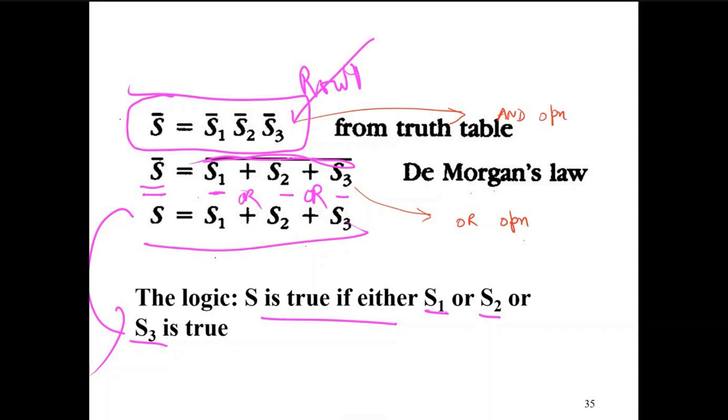What else? Well, I want to adjust that pressure. I want to press different types of materials, right? So I want to adjust the pressure for aluminum, I want to adjust the pressure for steel, I want to adjust for something else. So I want to know what is the type of material that is loaded onto the table. So I can put a material sensor, which is going to tell me whether it's aluminum or steel or whatever, and adjust the pressure automatically.